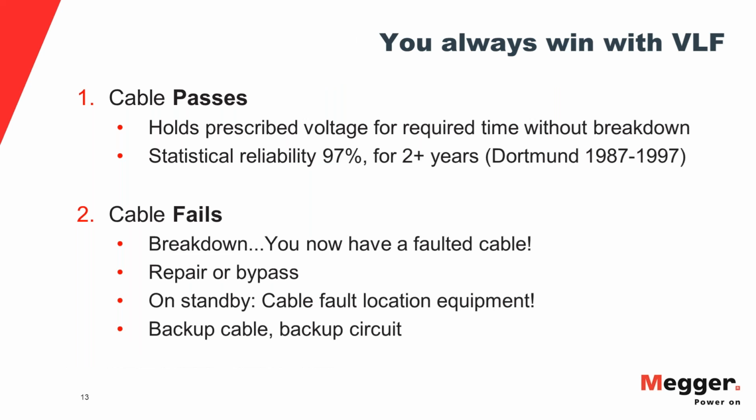So now, just as a comment on what you gain with VLF, I phrase this here as you always win with VLF, because when the cable passes the test, based on the international data that we have since many decades, you gain a statistical reliability of 97% that the cable from internal failures will not fail within at least 2 years, typically even 3 to 5 years, you can say. And if the cable fails during the testing, well, you need to be prepared.